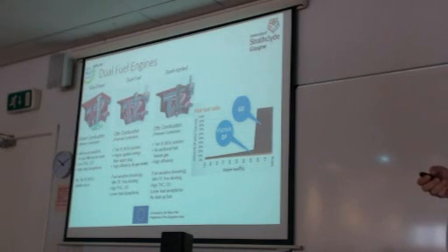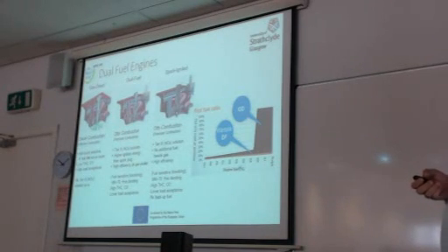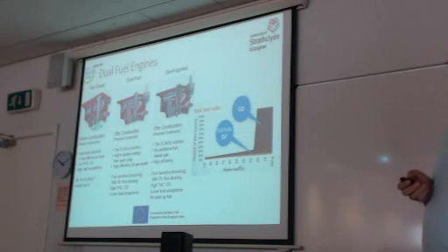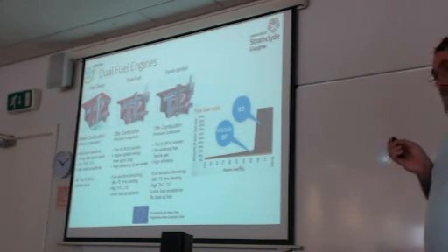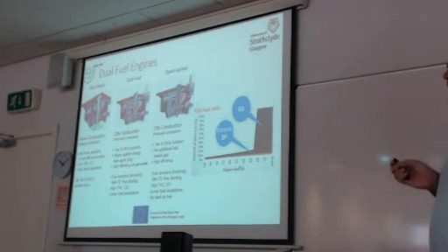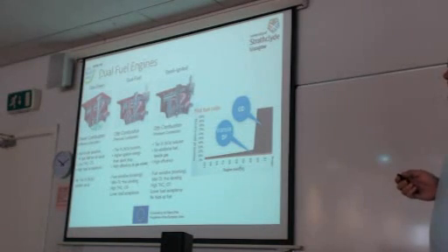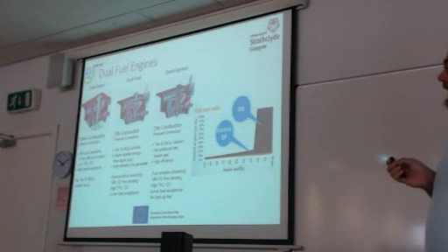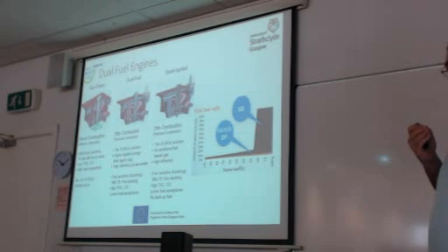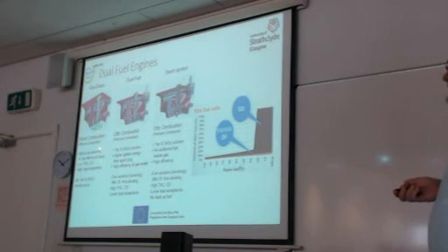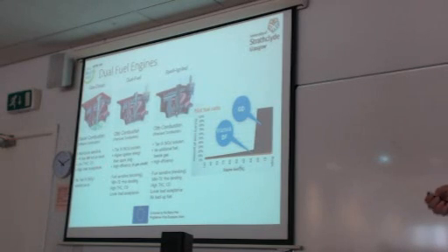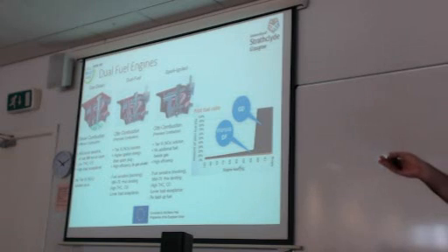So knock or knocking is abnormal combustion. We always need to avoid knock because it increases the pressure, so it introduces vibration in the combustion chamber, and is very dangerous. The engine components can be destroyed. In order to avoid knock, the fuel injection should be carefully selected, and of course we need to inject the pilot fuel before the uncontrollable start of combustion. So in the case of gas diesel engines, these engines are not sensitive to knock.